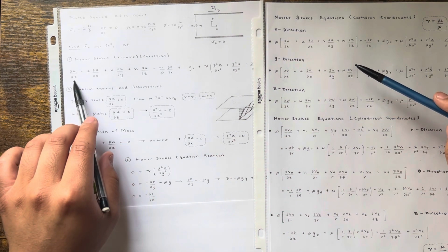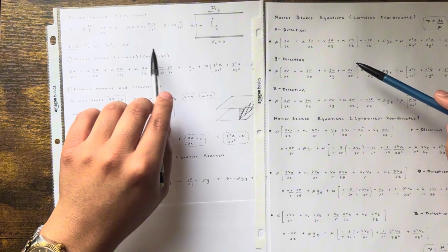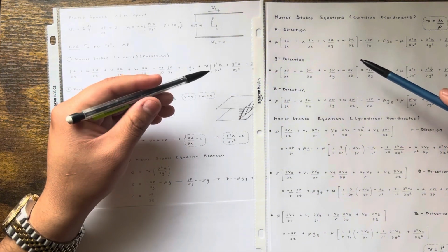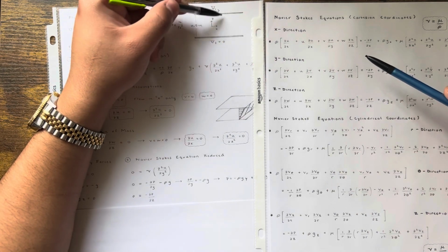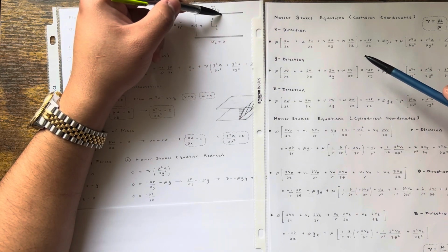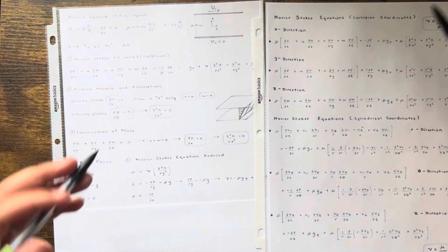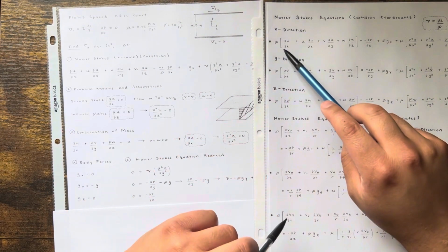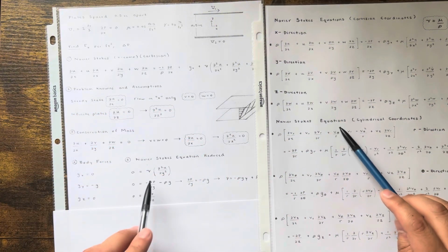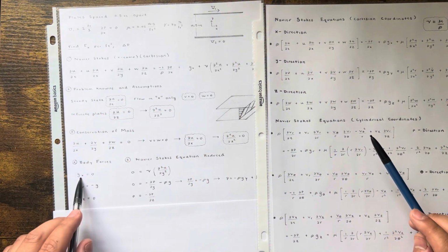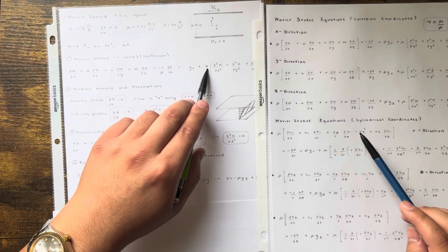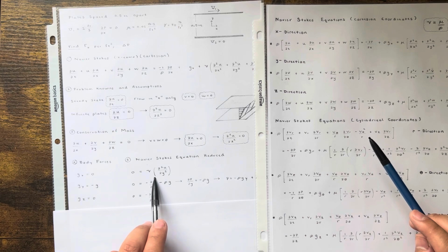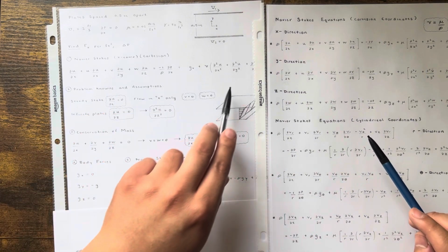Mainly, x is the one you've got to focus on because you're focused on the velocity profile in the x direction and how it varies along the y. Does it do this? Does it do this? Whatever the case is, right? That's what this problem is guiding you toward. In the x direction, we already simplified it all. As you can see, g of x was 0, so that went away too. So now we're just left with kinematic viscosity times this, and that's what I'm left with here, because a lot of things canceled out, remember?